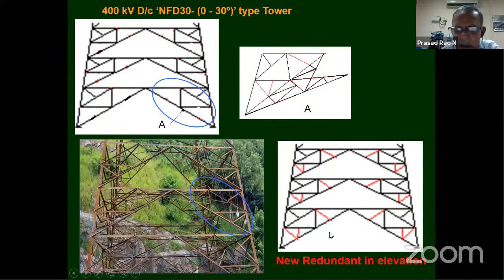So the advice is not to go for a secondary bracing pattern in such a way, assuming that it will provide the restraint for the out-of-plane buckling and in-plane buckling. For in-plane buckling, only elevation bracing can prevent. According to the designer, we have much capacity and other things. Still, it has failed because of this wrong assumption.